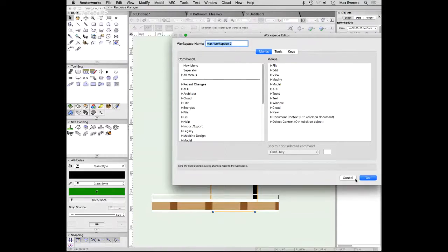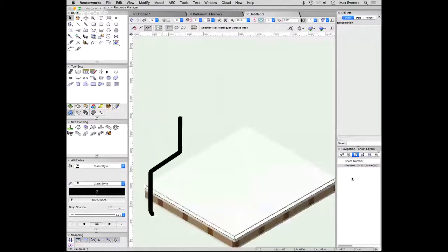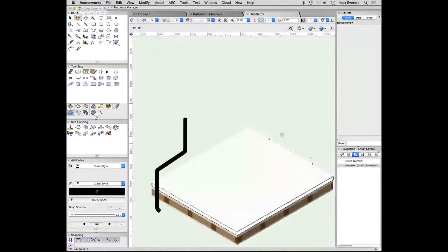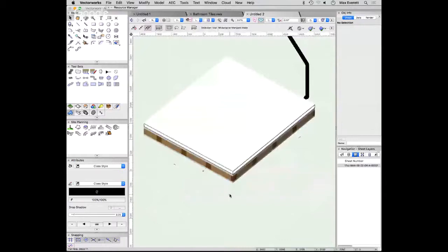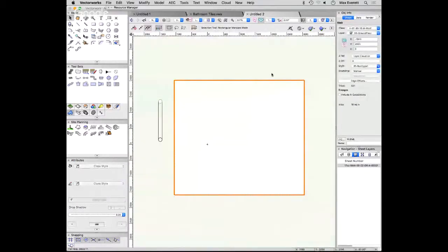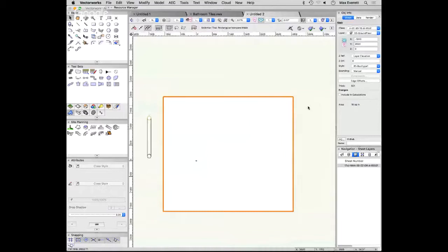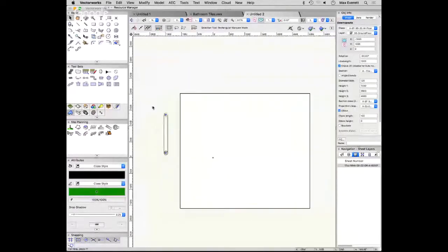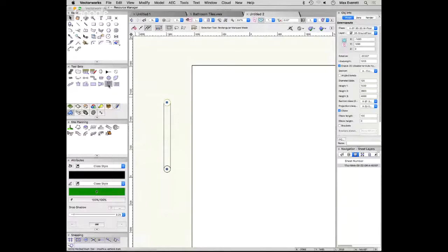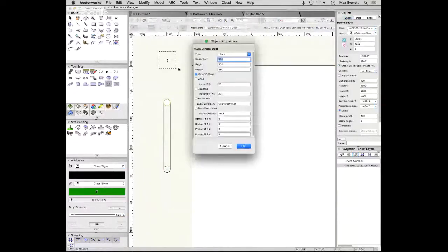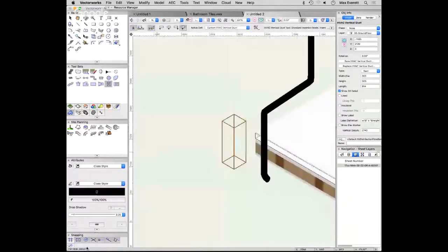So it's just two tools to do drainage. If you want to play around with the slab drainage, that'd be good to get. Holly's got it going on. I'll circulate the plugin for the rainwater pipe, because I think it's a little bit more accurate than using this tool, which is more to do with ventilation and heat. You can change that to circular and round, but it's not actually a rainwater pipe tool.